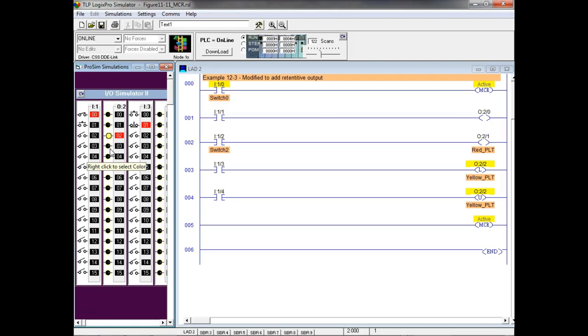So normally we would run this with a relay, with an internal relay contact. We use a normally closed. If we run it with one of our inputs, then we'll use an examine closed, right? That makes sense. So now I'm going to come up here and deactivate it. And now output 2/0, that's output. So output 2 doesn't work anymore, right? Now notice what happened here.